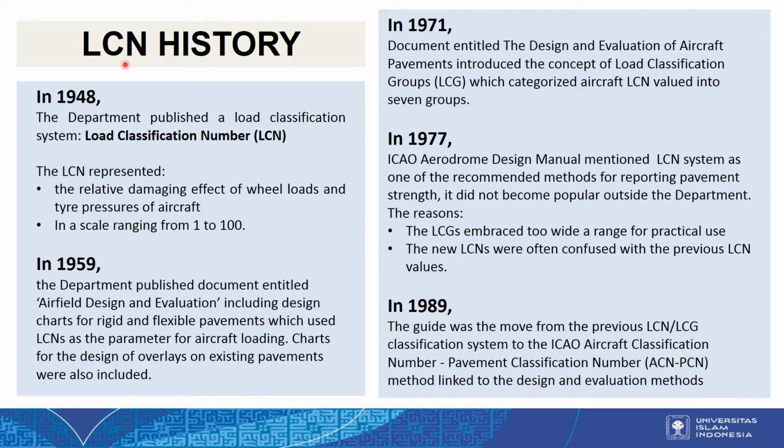For the LCN history, in 1948 the UK published a load classification system called the LCN, or load classification number. The LCN represents the relative damaging effect of wheel loads and tire pressures of aircraft.